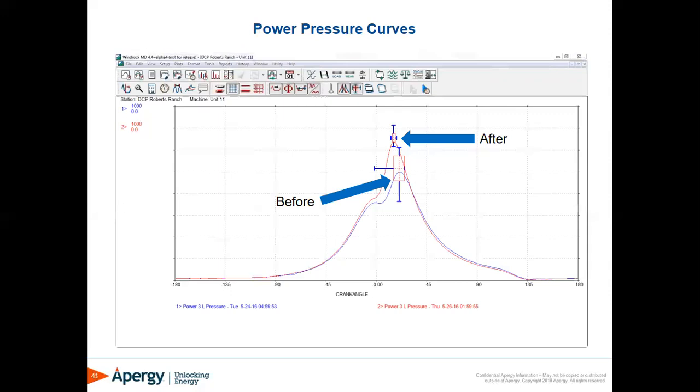So currently, for the example we went through today, the Windrock system is balancing the engine. It is taking the head and crank end pressures and the crosshead vibration. But we're not doing full monitoring. So you could still have a proximity probe for rod drop and rod runout. We could take ultrasonic data around the valves on both the engine and compressor. There's spark data that can be taken on the engine side. So there are still some items that are not collected by the online system.